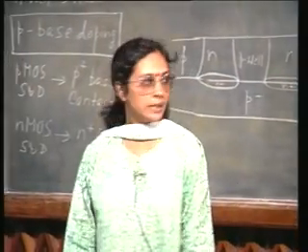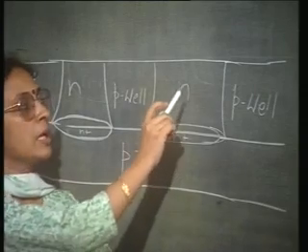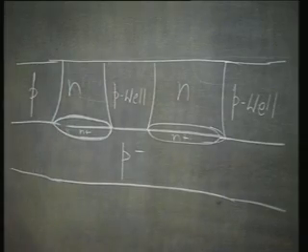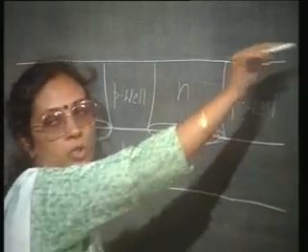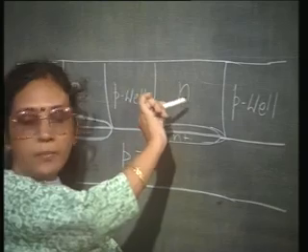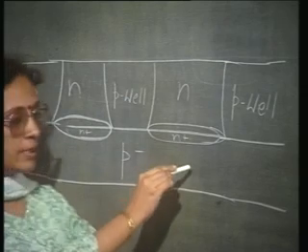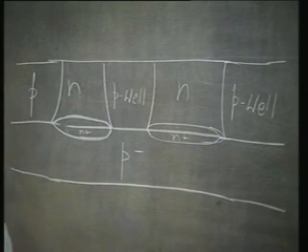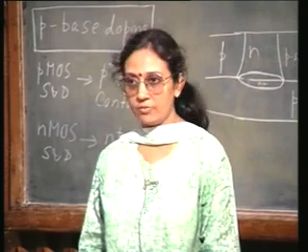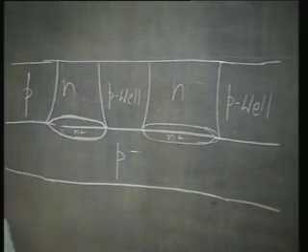Now, in this particular case, of course, we have a small problem. If I want to have another NPN transistor on this side, it must be separated well from the adjacent NPN transistor. Why? Because you see this p type substrate is very low doped, and necessarily your substrate is connected to the most negative point, right? So that this PN junction is actually acting as the isolation.